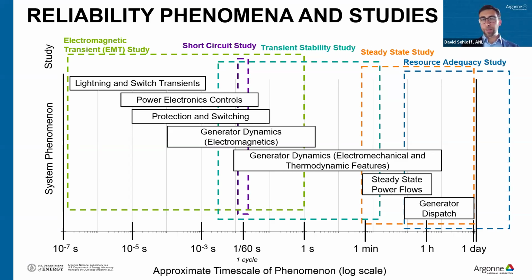Steady state is really looking at the system in its steady condition, where things aren't changing. We're looking at minutes to hours or up to a day. And then resource adequacy is something we won't touch on too much here, but that's looking at the generator dispatch going into days or even up to a year.